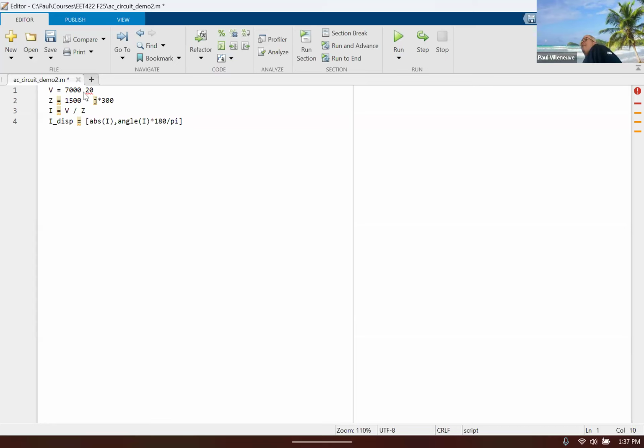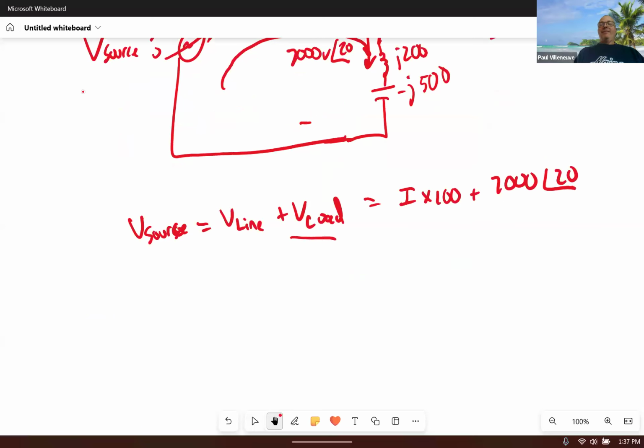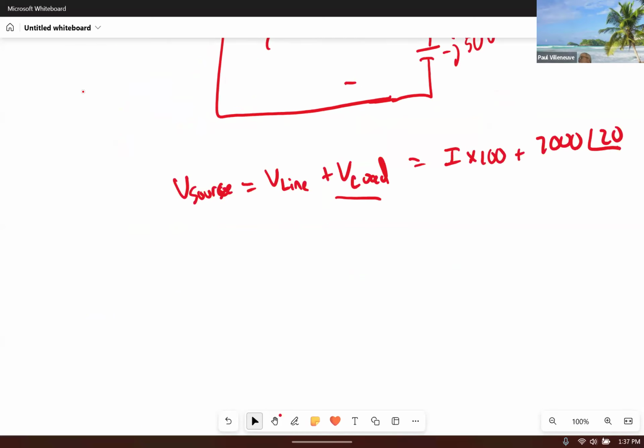Who here has a math minor or signed up for a math minor? Can I pick on you? Tell me the answer. How do you enter complex numbers with angles in them? You could do the cosine of the angle times the magnitude for the real part, and then add on a J, and then the magnitude times the sine of the angle. He's on the right track, but you're making it harder than you need to be. So you're right, it's not the most efficient way.